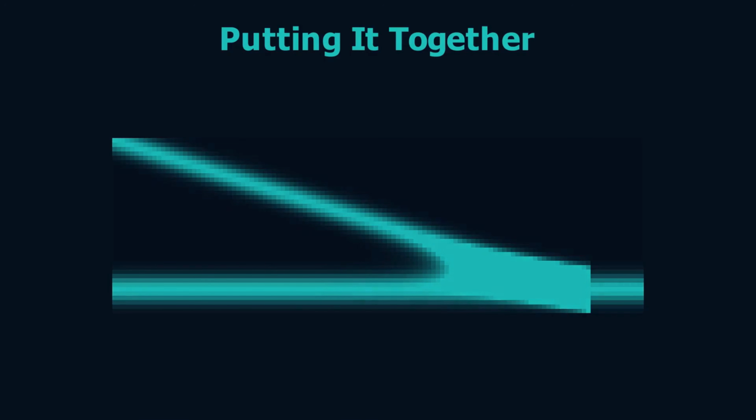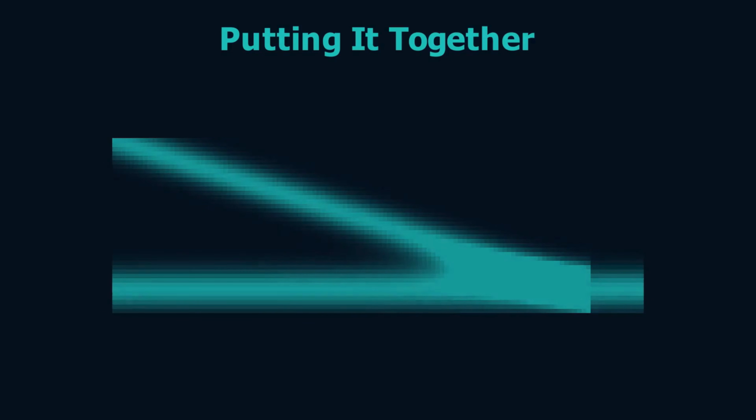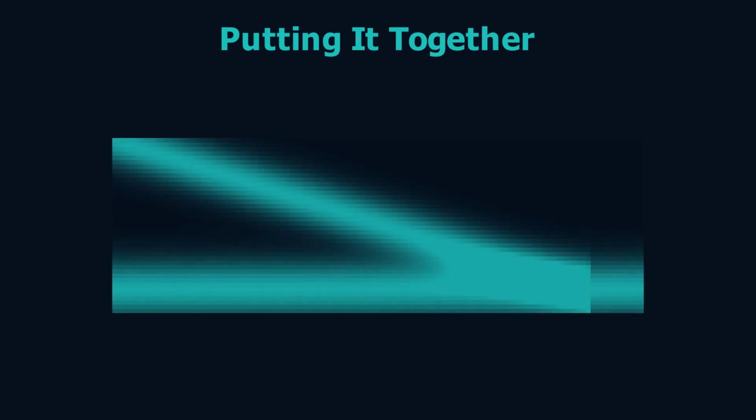The gradient pulls density toward the load path. SIMP makes the in-between values unprofitable. The filter holds every member above the minimum length scale, no checkerboard forms. The OC update moves material each step, volume pinned exactly on budget, compliance dropping monotonically. The members thicken where strain energy is high and vanish where it is not. Converged. Compliance 233.7 in 146 iterations, a number this repo generated and locked, not quoted from a paper.